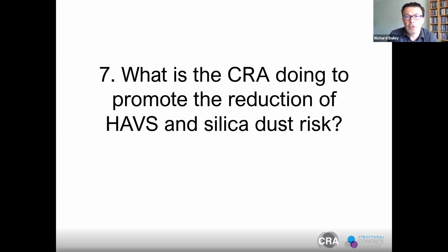So we need to look at automated solutions for raking out the concrete. That could be remote controlled electric robotic breakers, robotic units, pneumatically dampened and controlled air driven breakers. Hydro demolition is very well established, and in lots of circumstances it's a very appropriate way of breaking out concrete, and again takes the tool out of somebody's hand.